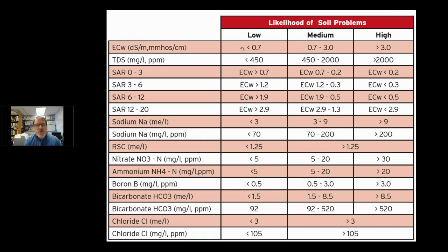So we end up having to amend soils with very low salt content with products like gypsum or calcium sulfate to allow that water to move into the soil. So you need to increase the salt in some waters to amend them to go into the soil. And I think we see almost equal number of problems with low salt water as we have with high salt water. Then the other factors we watch out for is the sodium content of the water and the residual sodium